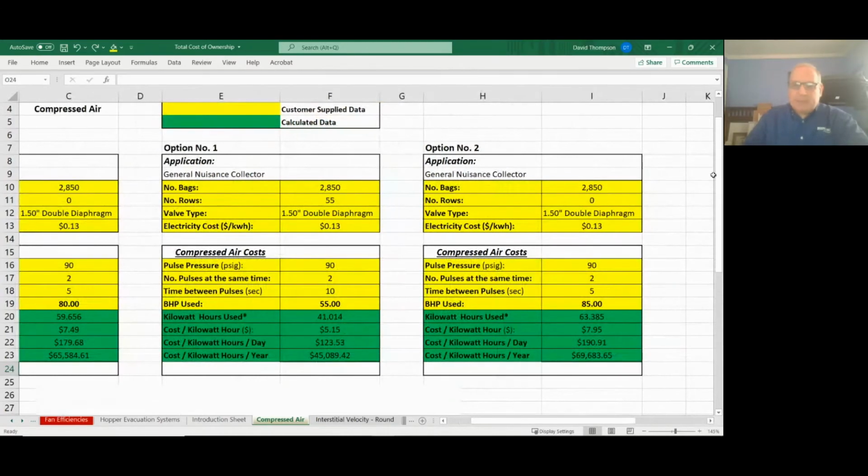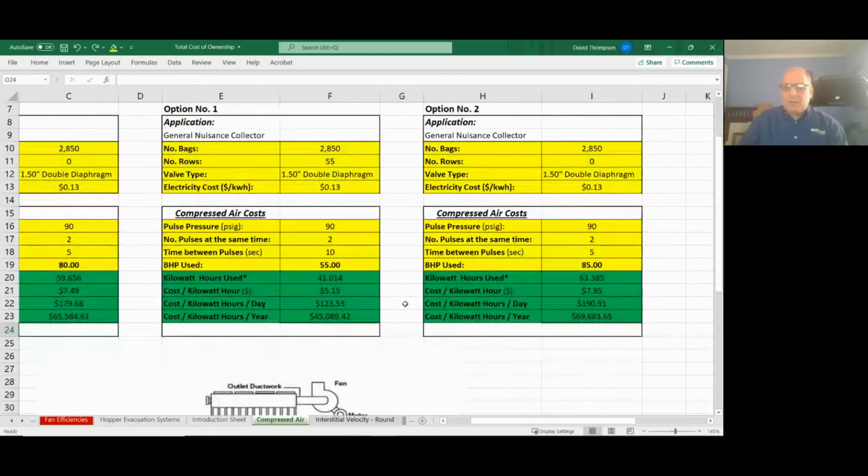Now, standard membrane bags still have a little higher differential pressure. You can increase the time between pulses, no doubt about it. However, because the differential pressure on that bag begins to creep, it does cost you a little more. You may reach terminal differential pressure faster, and you may pulse a little more. Again, you don't run the risk with a membrane bag of pulsing off the precoat, which is really important. We'll get into how we look at precoat and so forth as we go forward here.